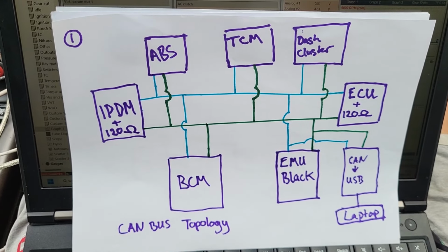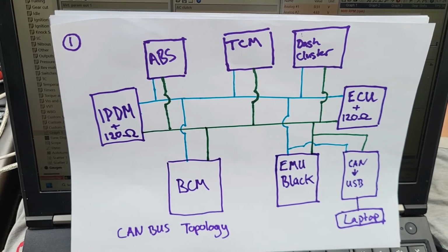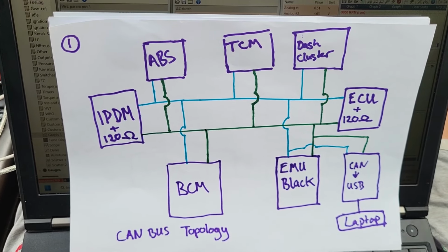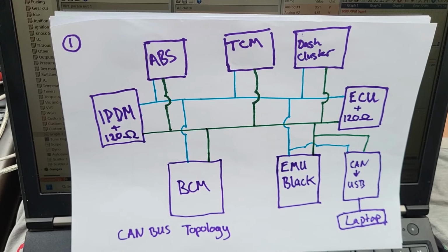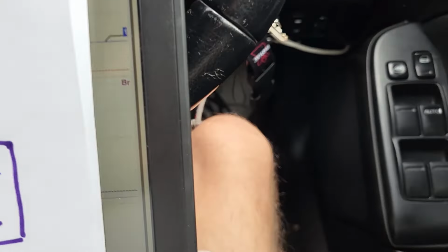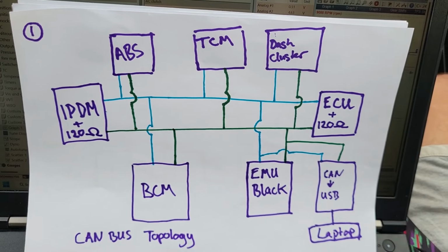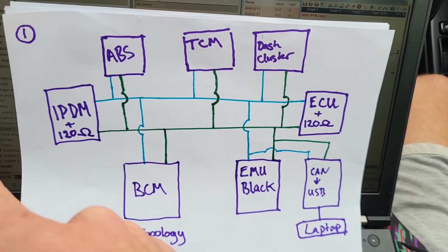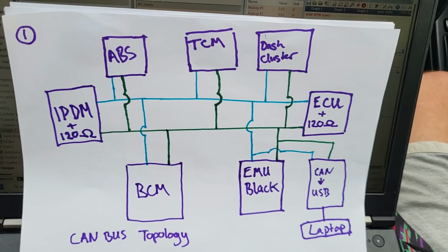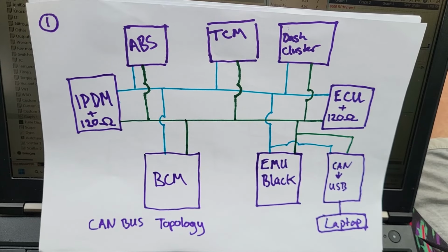We've actually had some pretty hot weeks here in the UK, so this summer I jerry-rigged a positive live to an analog input on the ECU, and then I had a switch down here, so when I wanted AC on, I flipped the switch, I got my rev boost, and then I pressed the AC button. So a crude way to do it, and it took up a whole analog input. So I wanted to get away from that.